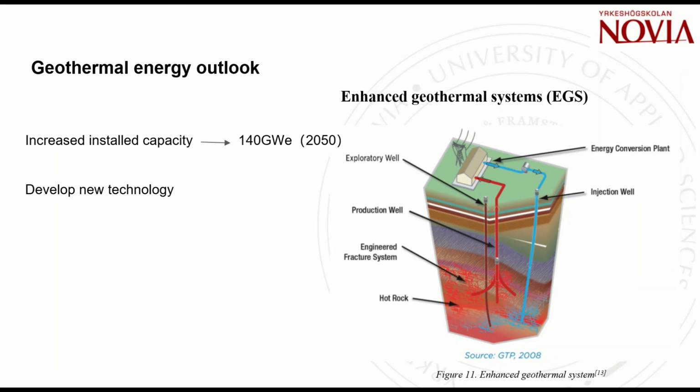If high-pressure water is continually injected to provide a stable source of water, these cracks may remain open. This method can make the location selection more flexible. The enhanced geothermal system is a man-made reservoir created in places with hot rocks but insufficient natural permeability or fluid saturation, which means that there is no need to build and expand power plants only in areas with geothermal water.